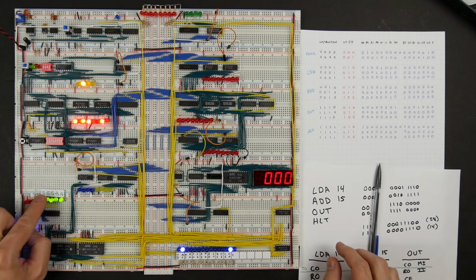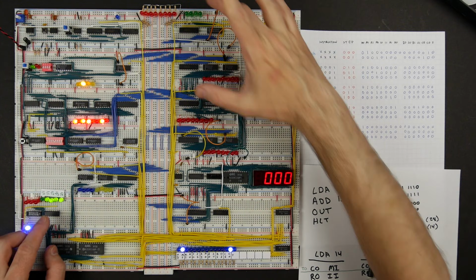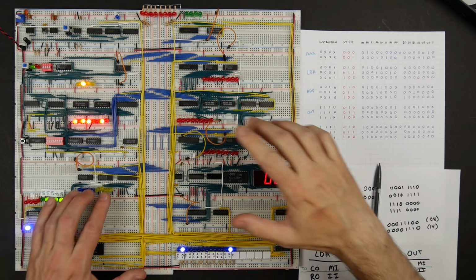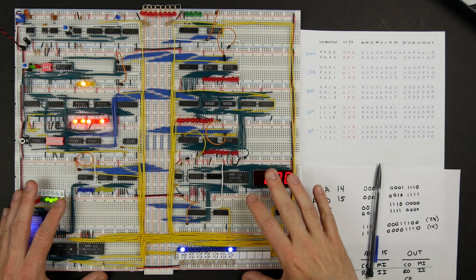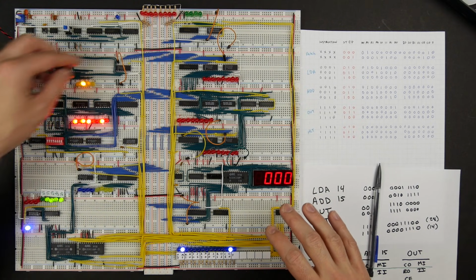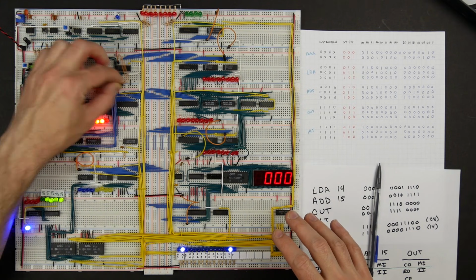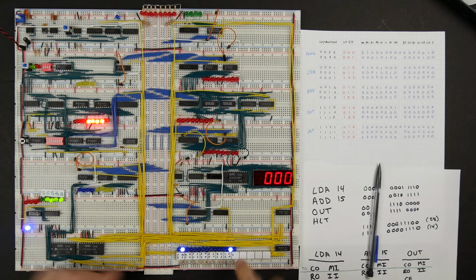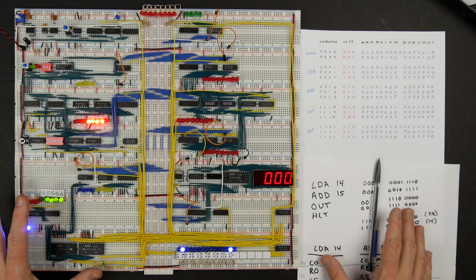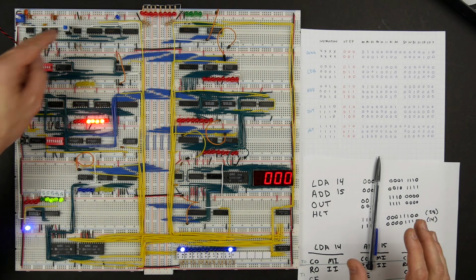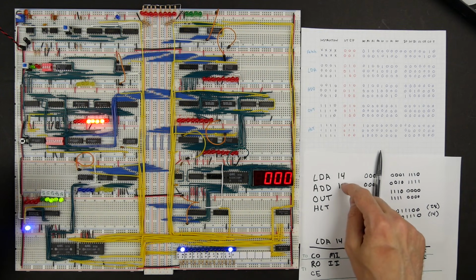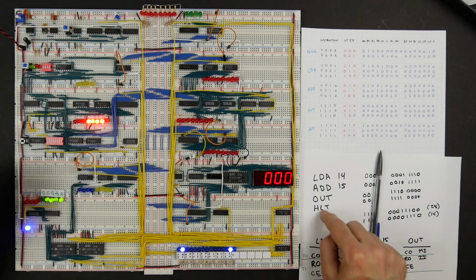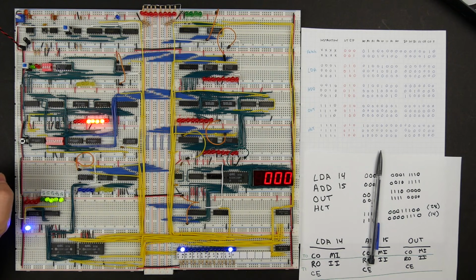Go back into run mode. Make sure everything's reset. So we're at time T0, so that's good. Program counter, A register, B register, instruction register, all zeros. I guess we could reset the memory address register as well to 0, although it doesn't matter. The first thing to do is to take our counter out and memory address register in. But I think that should be it. And so in theory, if we just run this program, it'll do that load A, add 15, output the result, and then halt the clock. And so we should see this halt light come on, and we should see the clock stop. So let's let her rip.